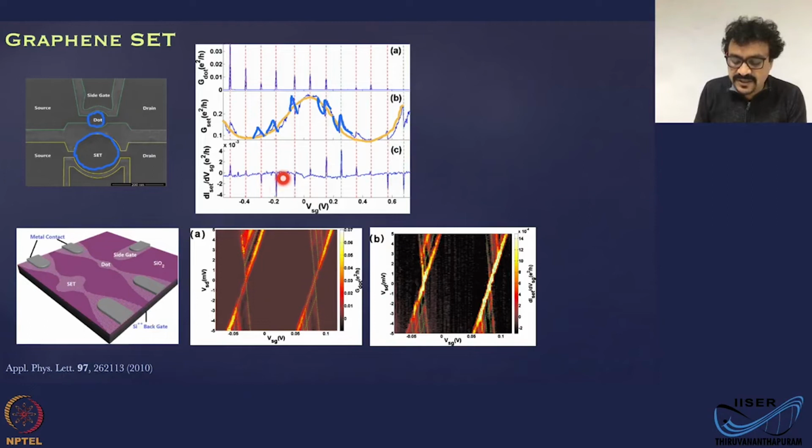And you can see all these sudden changes in the conductance of the SET coincide with the Coulomb blockade oscillation of the dot. And as I mentioned, there are many places where you don't see conductance oscillation, because those are not detectable, or current levels are very low, you can see here, but this SET is going to capture almost all of those things.